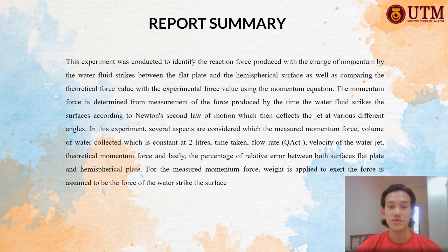So this experiment was conducted to identify the reaction force produced with the change of momentum by the water fluid strikes between the flat plate and the hemispherical surface, as well as comparing the theoretical force value with the experimental force value using the momentum equation. The momentum force is determined by measurement of the force produced by the time the water fluid strikes the surface, according to Newton's second law of motion, which then deflects the jet at various different angles.